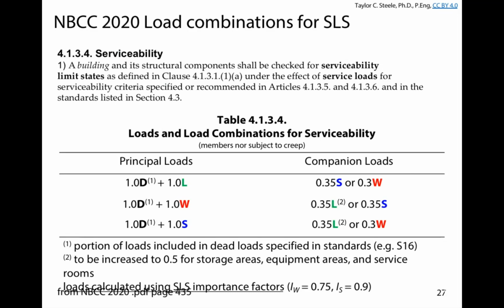In that light, we're going to use different load combinations. For example, later on in this course, we're going to be taking the deflection that we calculated from dead load or snow load or live load, and we're going to make sure that they're less than allowable limits. But we're not going to bump up the load effects to make sure that it's a really rare occurrence. We're just going to make sure that the deflection that's acceptable, that causes cracking, is more or less what we calculate it to be. In this case, we're basically going to calculate a deflection that might look like this, and we're going to calculate a load effect that might look something like this. And our goal here is more or less for the expected values for both those curves to be in alignment.